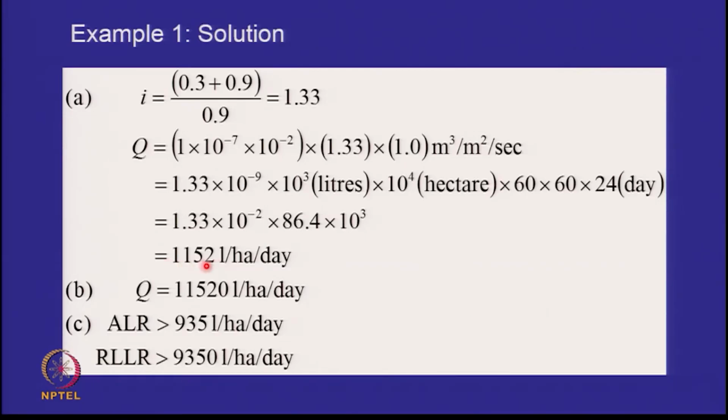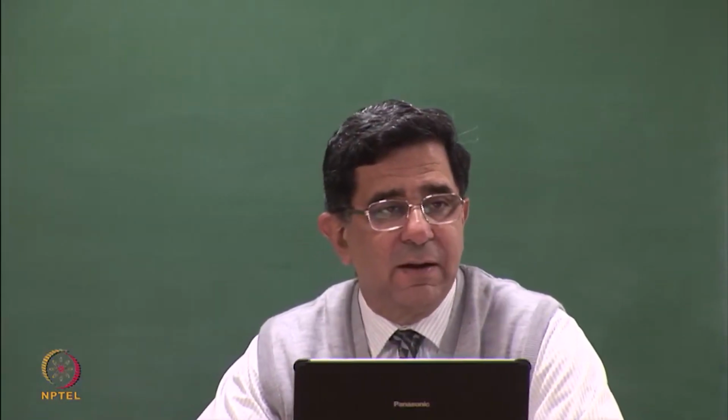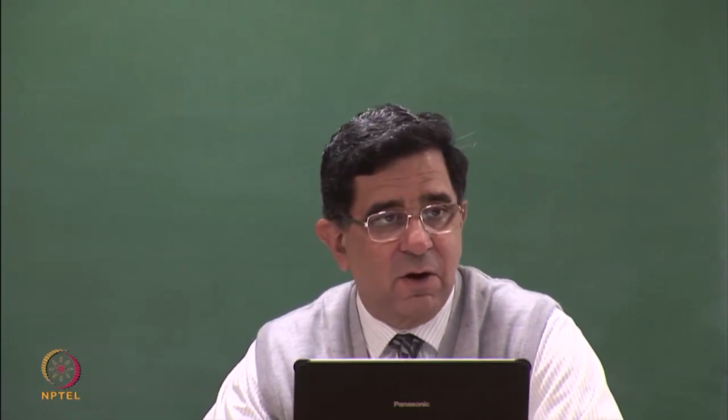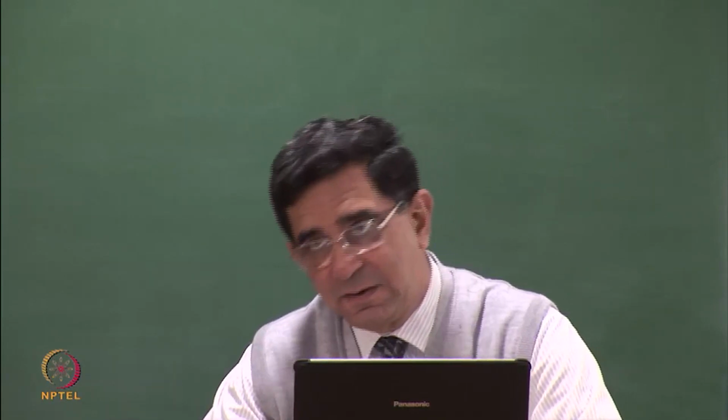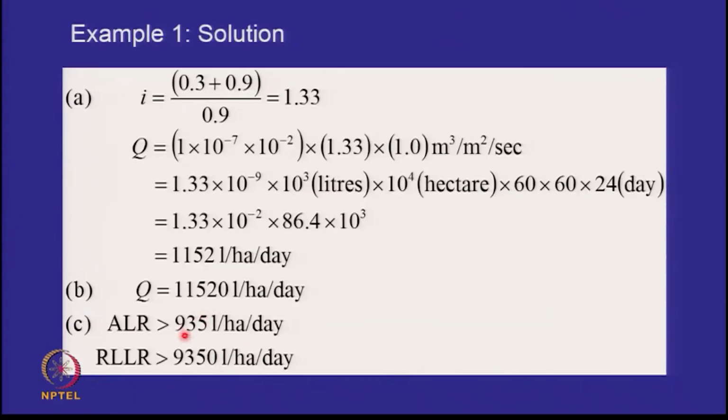So what we have to see is that if I have a good, well compacted clay liner, I'll get 1000 liters per hectare per day. Okay? And if a bucket is 20 liters, how many buckets is that? 1000 liters? 50 buckets per day. So if you compare it now with the action leachate rate which we had talked about, that it is 935. 935 is the same as 1000. So the 1000 comes from this. That means if it exceeds 1000, you have something to worry about.